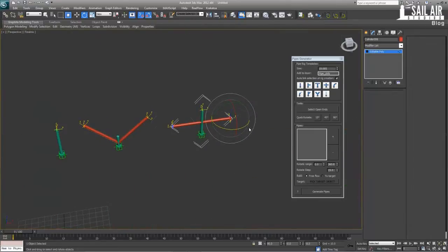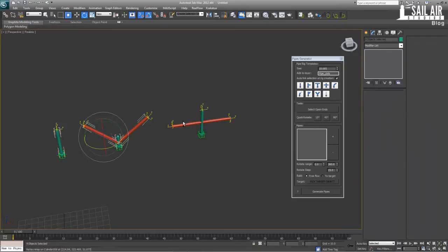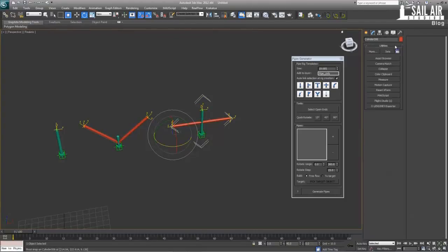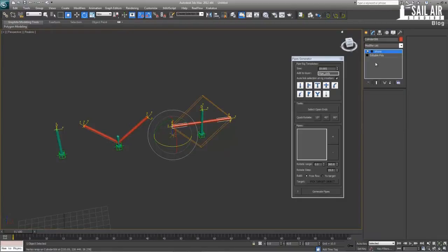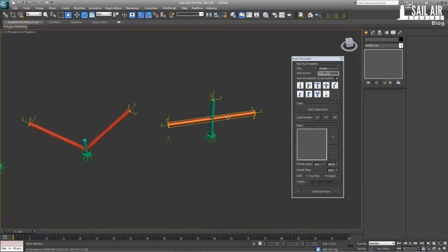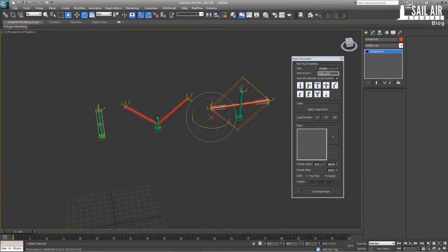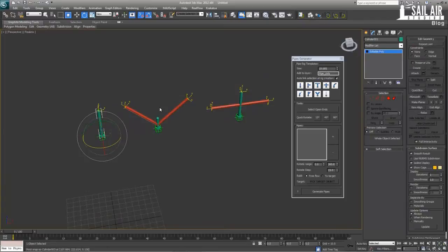And these aren't my best models, as you can tell. Not about the models in this one. I should reset the XForm on this section. What resetting XForm does is, you can see the bounding box is like this, but I want it to conform back to its original thing. It's because of the way I rotated it and changed it and all that stuff. Reset selected, and you can see that's an XForm modifier on it that resets it to the best bounding box it has. It resets all the XForm transformations I made to it.